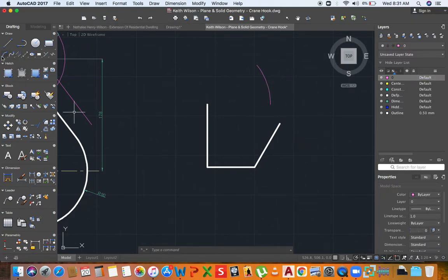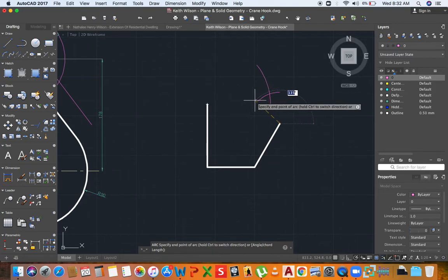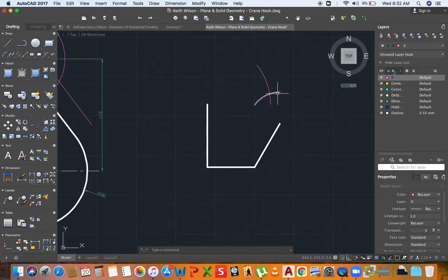I did something wrong. So I click the arc, then press C, enter. Click on the point where the pivot point. This would be your compass point. Then you're going to stretch and type 50. Then you're going to swing anti-clockwise. And if you notice, it cuts the lines, they intersect. Then you're going to go back to your outline layer.